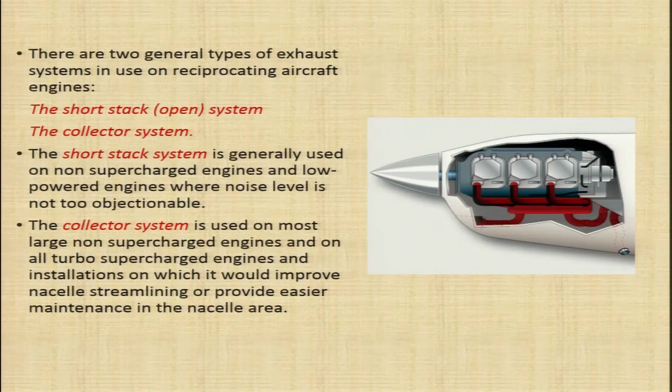The collector system is used on most large non-supercharged engines and on all turbo supercharged engines, and installations on which it would improve nacelle streamlining or provide easier maintenance in the nacelle area.